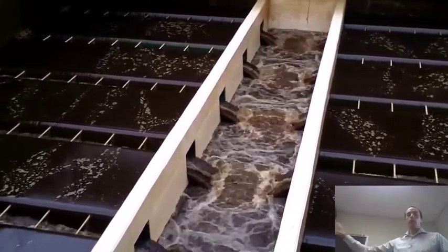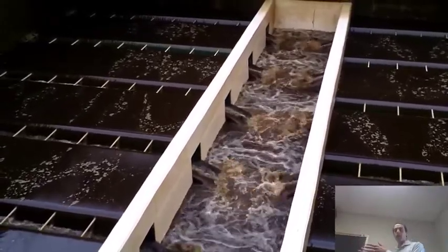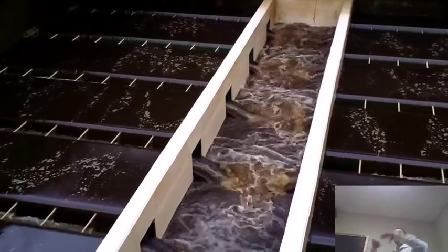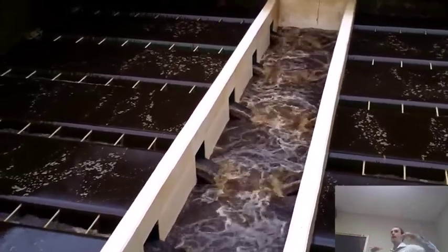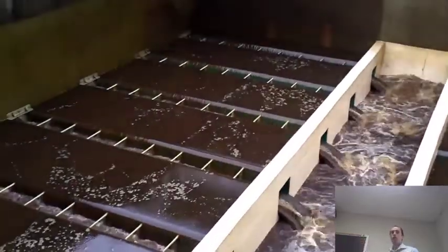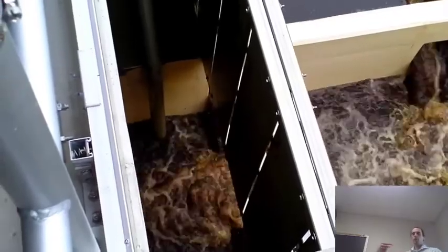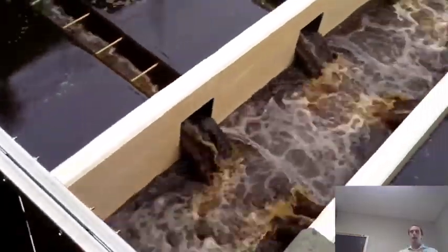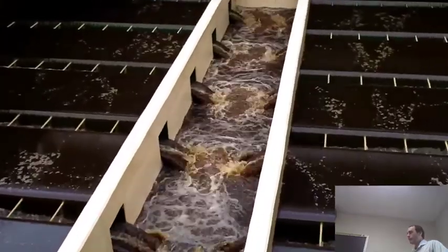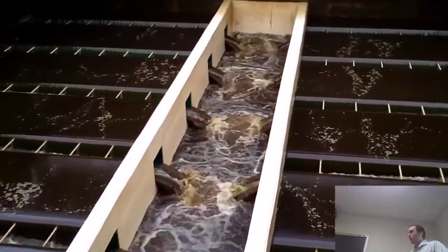You have the water that you want to treat coming into this main middle trough, and then overflowing and distributing across these smaller troughs into your bed. So normally the operation is literally reversed from this. They just literally reverse the process and then change where this water is going. Instead of coming into that pipe, the water can go out there and go to a waste line to be processed by a wastewater treatment process.